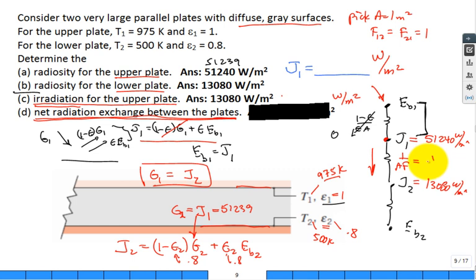If you want to use the units, 1 over meter squared, you know. So what's the flow through this when I have a potential and a potential known and a resistor of 1? The flow is the difference in the potentials divided by the resistance, divided by 1. So just like somebody said, this Q double prime, because it's a per unit area, is just going to be the J1 minus the J2. Yeah, so we'll go ahead and look at that.